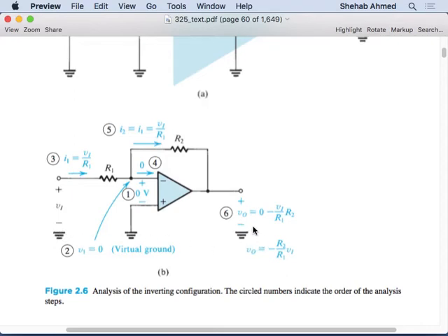From the perspective of building the circuit, this is a simple circuit, right? But when you have a very complicated circuit with a DSP, a signal processor, an FPGA with some analog signals and some digital signals, some high-speed signals, some low-frequency signals, high-magnitude or low-magnitude signals from a voltage perspective, high-magnitude or low-magnitude signals from a current perspective, all of this changes everything, right? How to set up the ground for each and every one of them, I cannot comment on that. It's a science. With simple circuits, no problem, just put a common ground. It only becomes important and very difficult when you talk about very complicated circuits like that.